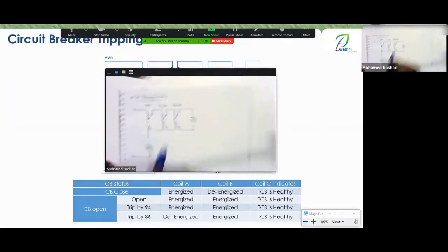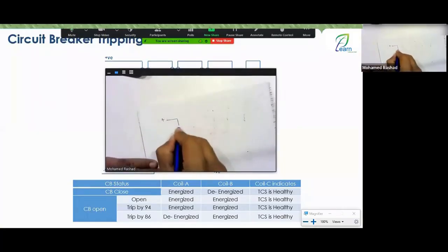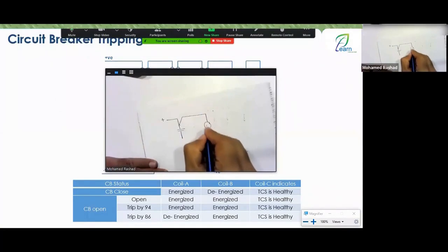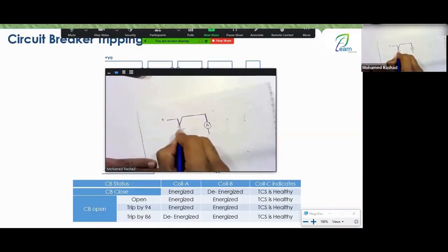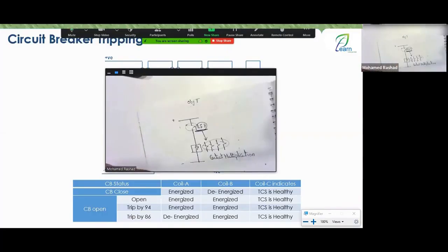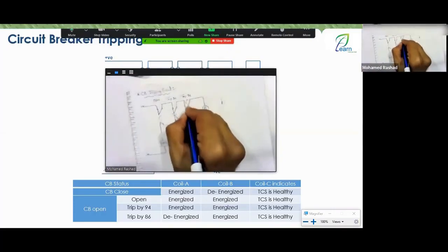Let me draw it for you on the side. For example, here it is. Imagine if this was the positive, and I come here to this contact and exit here with a block like this, showing the regular DC, and I come here to coil A. Now, if the wire going to the contact itself is cut, coil A wouldn't lose the positive. The positive would continue normally, right or wrong, right? So it wouldn't perform what? It wouldn't perform complete supervision. That's why this is wrong, and I start monitoring up to the wire from the head of the contact.